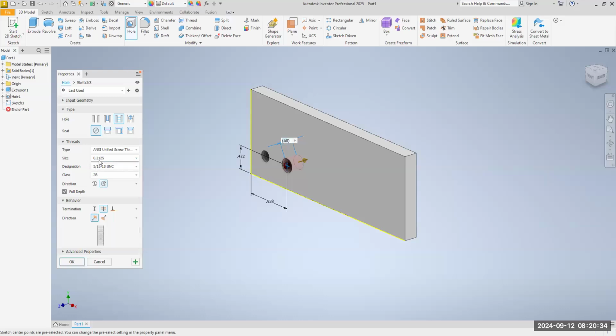And then this is a check. Look, if you get it wrong, you can see we're correct because there is a designation. The diameter is 5/16. Do we have the right number of threads? It says 18. Is that what our table says? B1 says 5/16, 18. What is UNC? Unified National Coarse, right? It's a coarse thread. Because we have fine threads, we have coarse thread. This is a coarse one. We want to go to full depth.